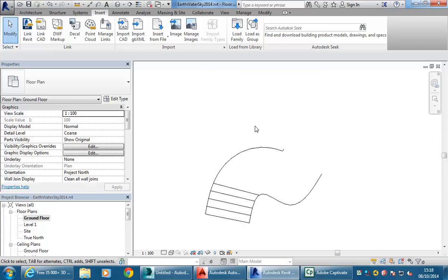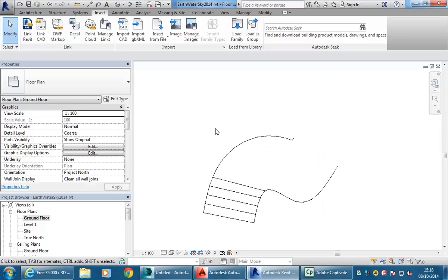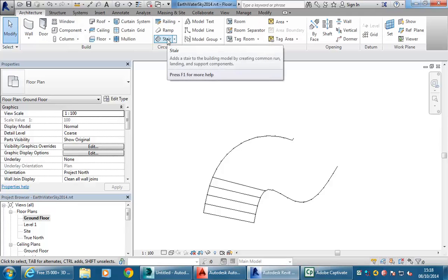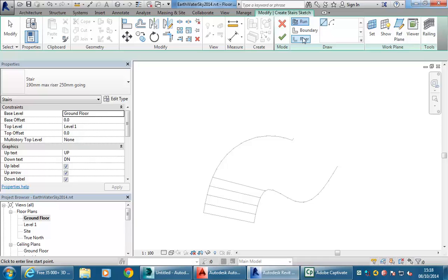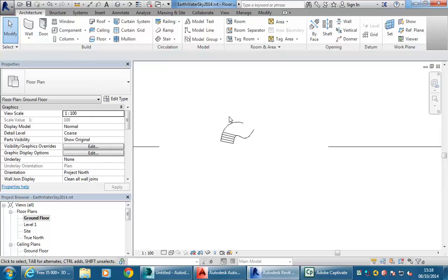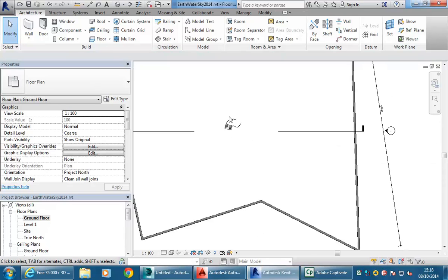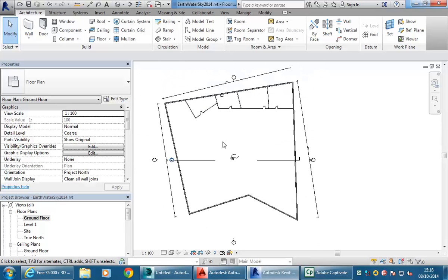And then would you maybe have to scale it up if you have another measurements wide? Yeah, that's why. I mean, that is a metre wide because I've done it that size in AutoCAD. So now I could either use the Stair Tool in Revit and try and use stair by sketch. Stair by component you probably found is pretty cumbersome most of the time. It gives you usually too much and definitely more work to do. So stair by sketch I could use to pick the sides now using boundary and riser. I won't do that. Or I could go into 3ds Max from here and do the modelling there if I wanted to. So again, just trying to get you thinking about that linked workflow.